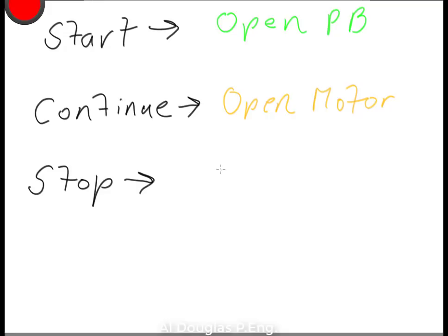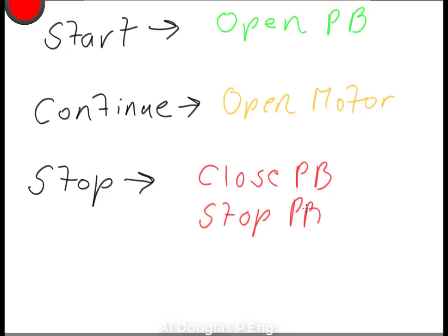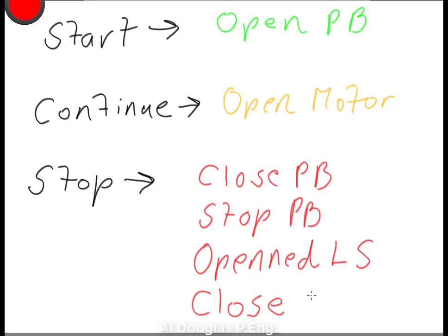Now we will stop if we have the close push button, if we have the stop push button, if we have the opened limit switch, or if we have the close motor. Let's add all of those things in here.